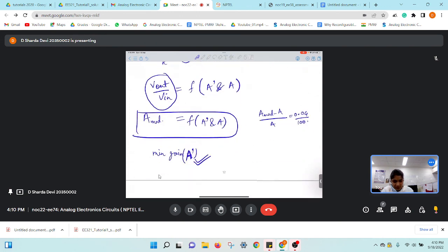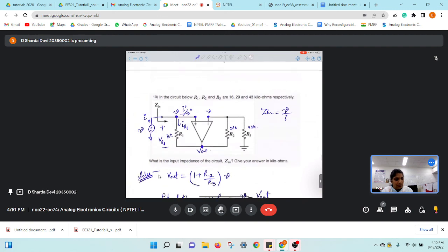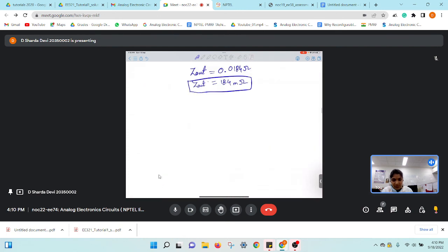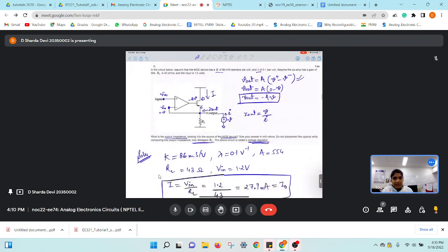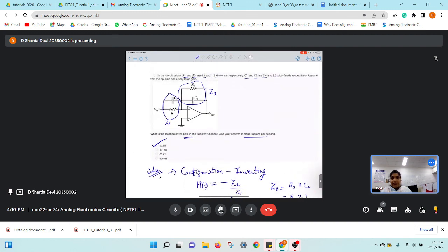Okay, so this is a different type of question. This time I guess we have touched all types of questions which are present in the assignment. So any doubts in the questions that we solved today? Any concerns? It's already 4:10 right now. Anything that you could not understand? Whenever there is an op-amp and nothing specific has been mentioned, we always have to keep a few things in mind. Firstly, the virtual short concept. If nothing has been mentioned about an op-amp, you will simply apply that virtual short concept. The current going inside an op-amp through the input terminals is 0.